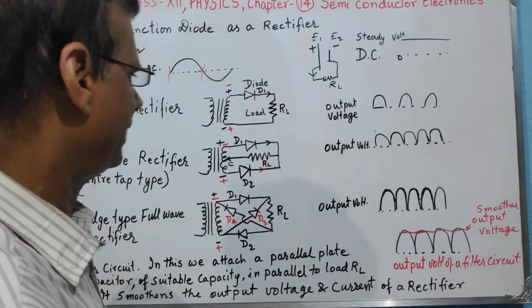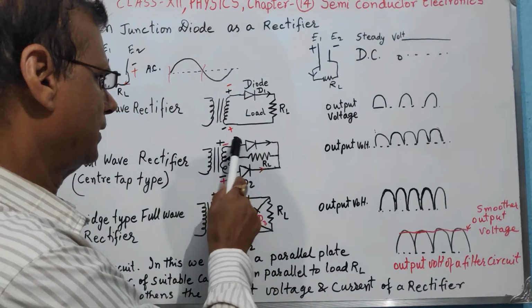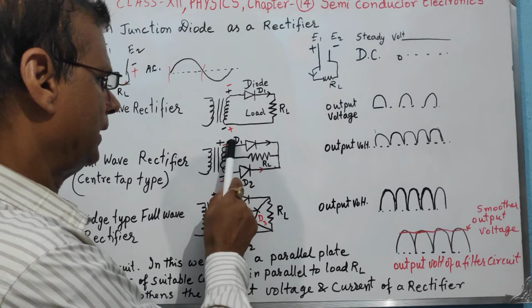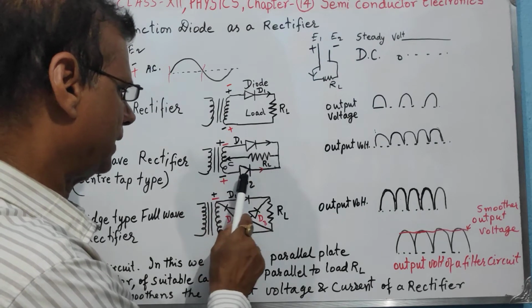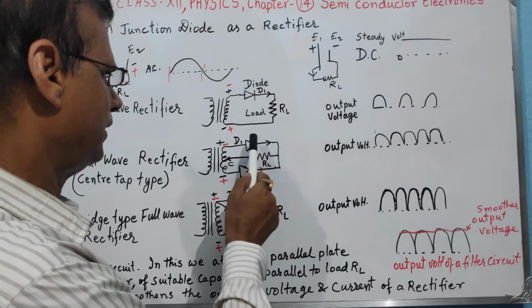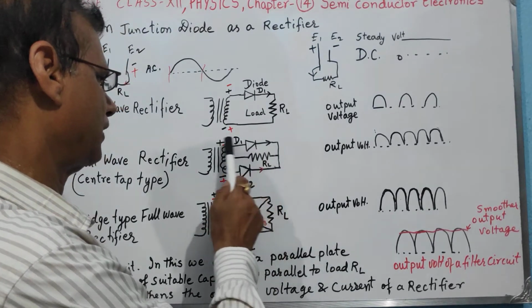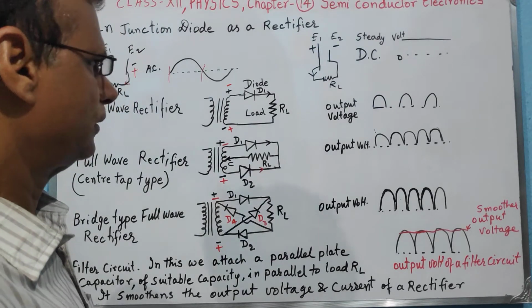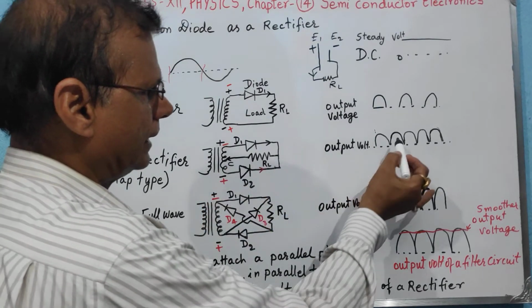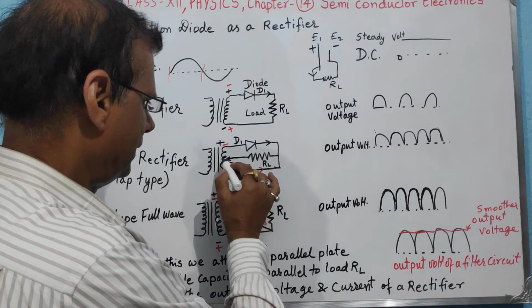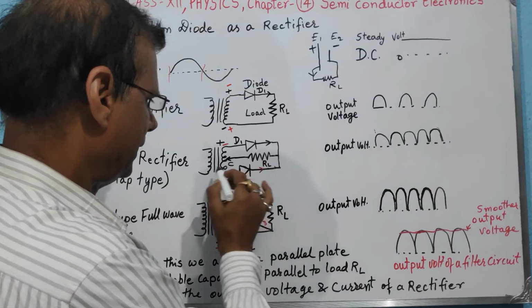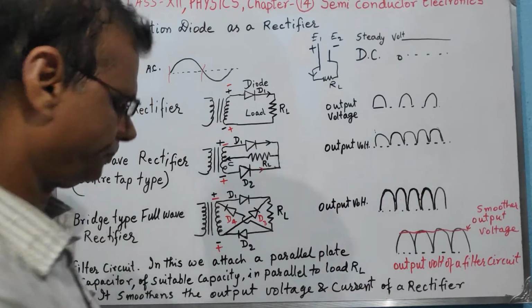This is because in this situation diode D1 is reversely biased, because the upper part of the output terminal is at lower voltage and the lower part is at higher voltage. So D1 is not conducting, and no current is passing through D1. Therefore in the second half cycle the lower part of the transformer actively gives the energy, and AC is converted into DC.